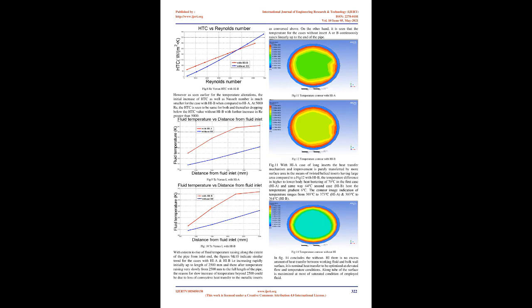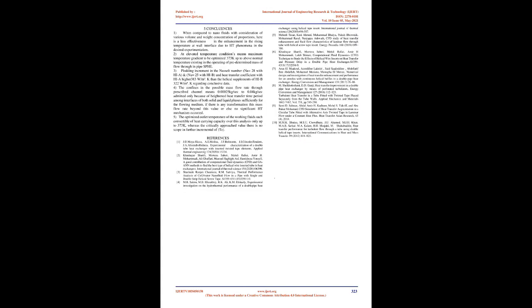3. Methodology. The single pipe heat exchanger is numerically investigated with helical tape inserts placed inside the tube. In the case of HIA, twisted tapes are inserted throughout the pipe length, and in the other case, HIB, twisted tapes are placed only in some extent of the middle of the pipe. So, in both cases the flow should have the same operational conditions like 1. Flow is incompressible and velocity of the flow is constant for each operating condition in both laminar and turbulent regimes. 2. Assumed flow is 3-dimensional, steady and uniform throughout the length. 3. Fluid properties are constant and gravity and viscous forces are neglected.